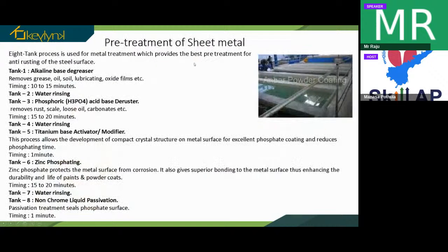Say we prepared a component from so many sheet metal operations, and then we have joined it using welding. Then, to take out the excessive particles or excessive metal that has been deposited on the sheet, we use the sanding process to take out all the excessive metal deposit.